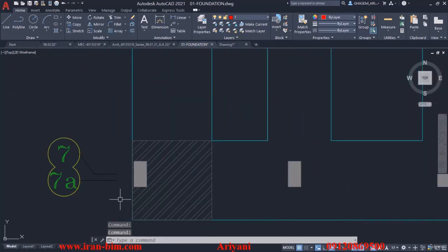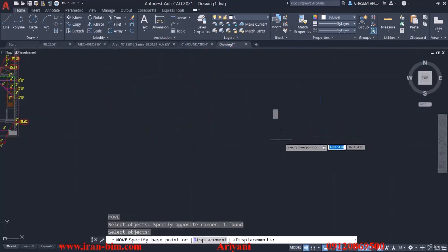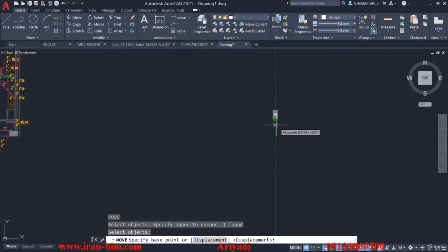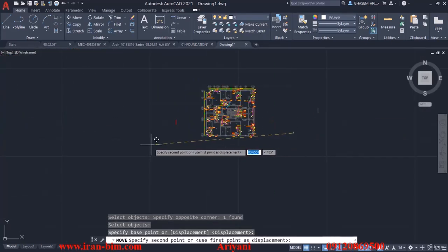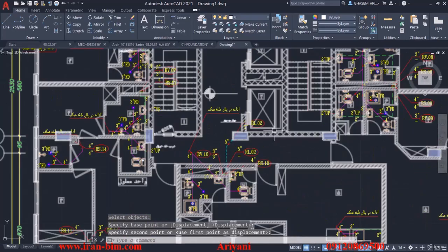So I'll select it and then select this aux as well, then hit Ctrl C and then Ctrl V over here, plus enter, and then on the shape that we have we'll select this corner down left and insert it to this corner in the plan.